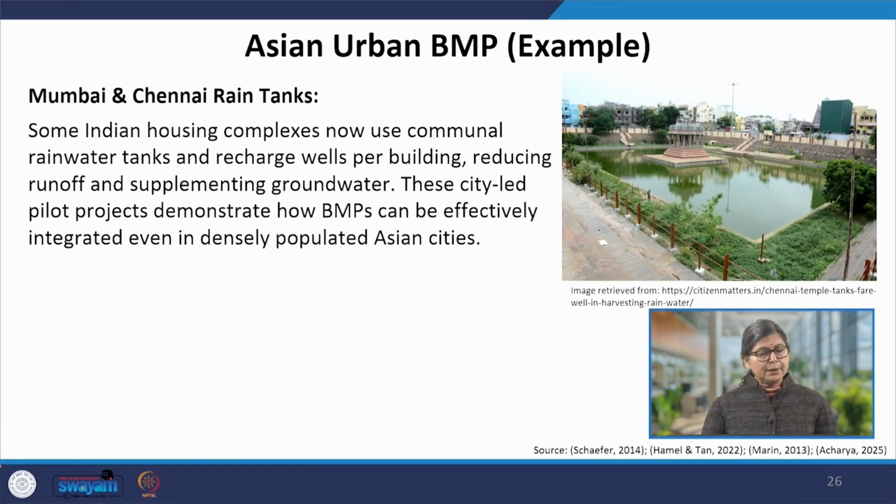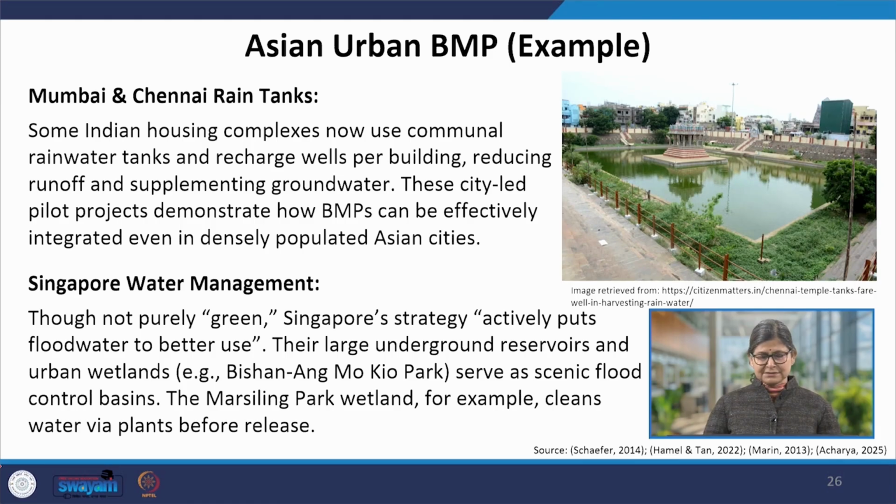Asian urban BMP, Mumbai and Chennai, rain tanks. Some Indian housing complexes now use communal rainwater tanks and recharge wells per building, reducing runoff and supplementing groundwater. These city-led pilot projects demonstrate how BMPs can be effectively integrated even in densely populated Asian cities. And I would like to remind you that what we do not only in Chennai, the temple tanks and the traditional tanks, we discussed also the Warangal city, if you remember, cascading tanks.